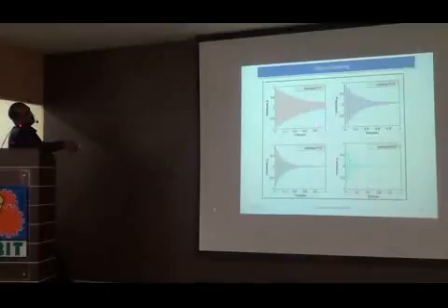Compared to this, this has come more quickly. It means this has better damping than this. This one has come quickly, much better than these three. So this has more damping. Ideally, the materials that we can use are steel, aluminium, and magnesium. Of all the three, magnesium has better damping. So we use magnesium alloys for most of our fixtures.